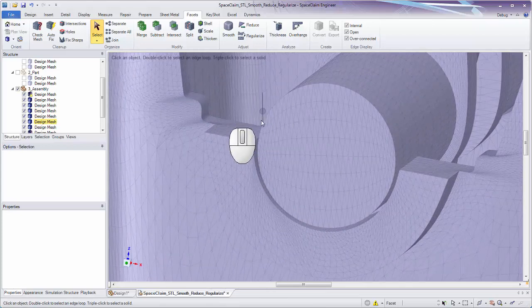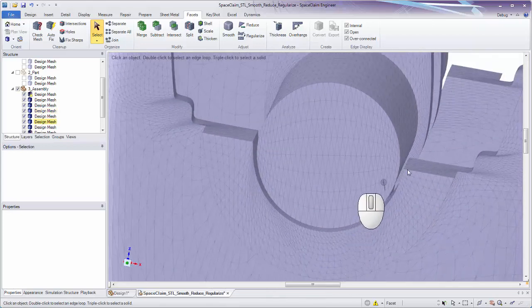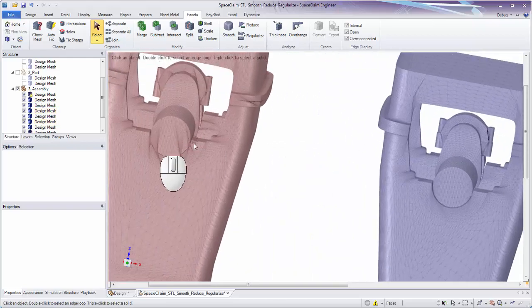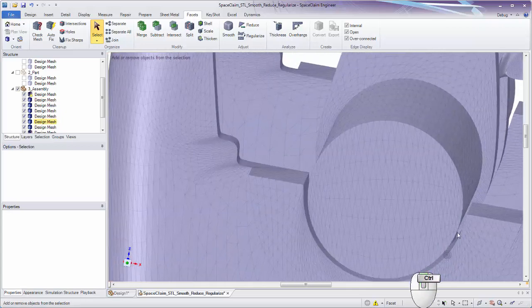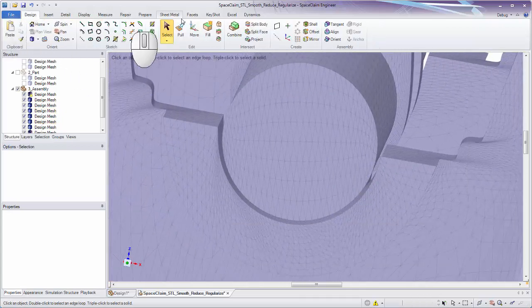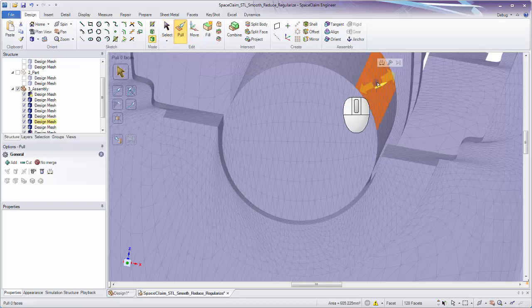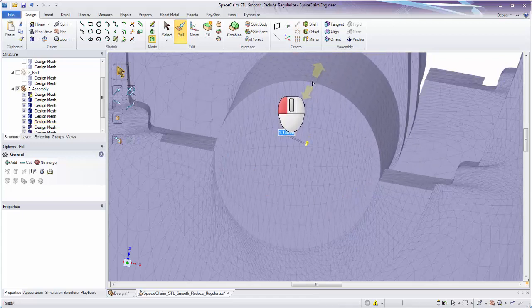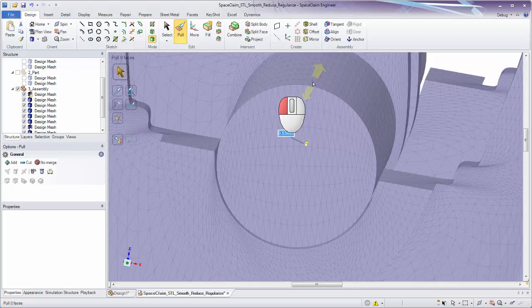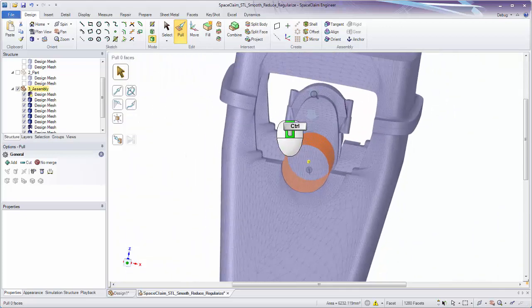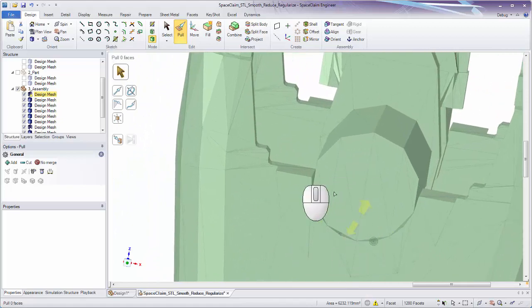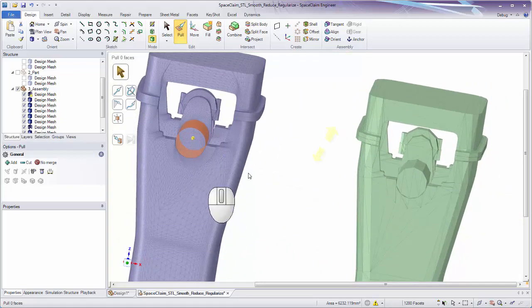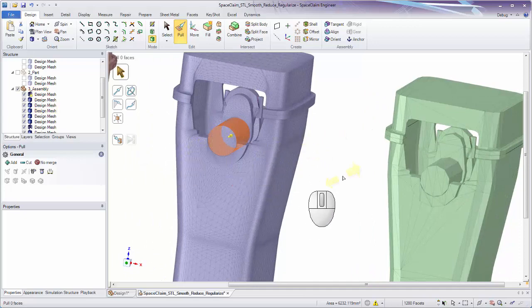And we can see that we have the correct smoothing, the desired smoothing. We have a nice, clean cylindrical hole and a cylindrical pin, as opposed to over here when those actually remained attached. And similar to the last part, we could always take the pull tool, grab some facets. We can double click in a couple different areas to grab the whole thing. And you can see that I can drag this bigger and smaller with the pull tool in order to get it to fit correctly. So sometimes the original part does not have the correct resolution, and smoothing it out on an assembly requires separating, and then other edits can be made to get the desired sizes.